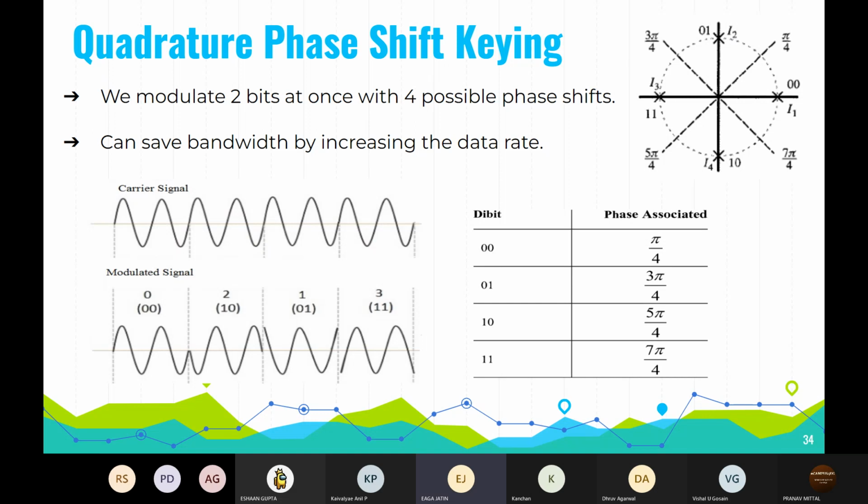So this is the difference between BPSK and QPSK. Now it can select one of the possible carrier phases from 0 degrees, 90 degrees, 180 degrees or 270 degrees. So out of the 4 phases, it will select any one phase in the carrier. QPSK allows the signal to carry twice as much information as the original PSK using the same bandwidth. So here we can increase the data rate as it will carry twice the amount of information than BPSK.